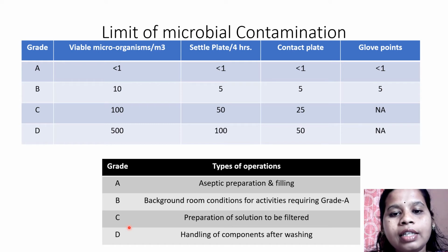This area is critical because an exposed product can be vulnerable to contamination. To maintain the product sterility, aseptic operations are performed at a controlled and maintained appropriate quality. Grade B is the background for the operations conducted in grade A. Grade C is necessary for filling of the products or preparation of the solutions that are unusually at a risk